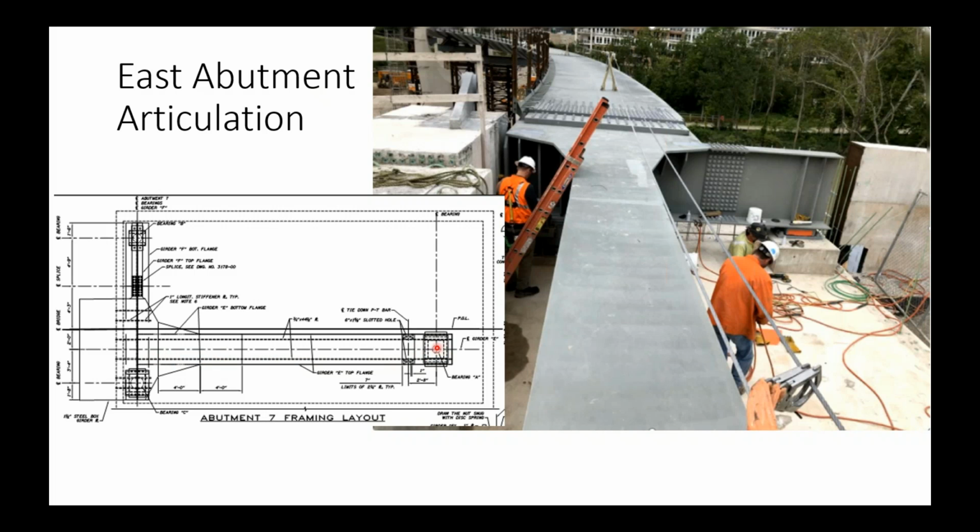And then we put an extra bearing down here. This will be a tie-down bearing. It'll act to hold down the back point of the bridge and create a force couple, a 30-foot long moment arm to create a negative moment here at the support and generate the additional stiffness that will make this bridge deck act a lot better in its deflection behavior. So that's kind of a unique feature of this bridge.